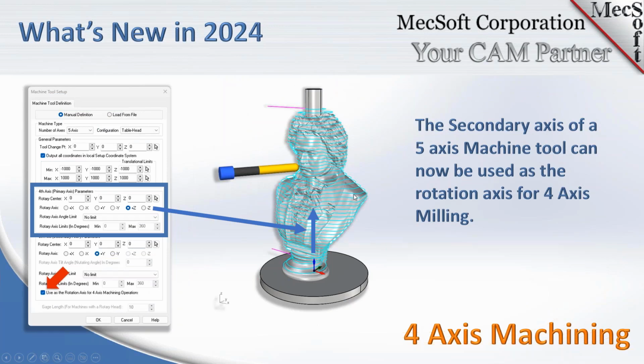Now also, we allowed you to machine and change the rotational axis of 4-axis machining to the positive Z and negative Z axis. For instance, in this dialog over here in the machining dialog, we have the machine set to 5-axis, but we have the 4th axis rotation set to plus Z or minus Z, and check this box down here to use that for the 4-axis machining operations. Previously, we did not support the rotational axis in the plus or minus Z axis of the part.